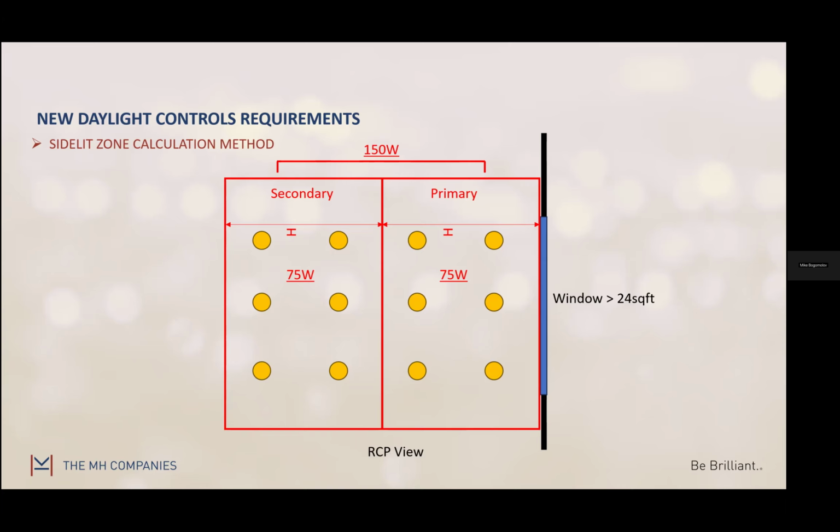Local timer switches. So yeah, schedule based. I guess by timer switches they probably mean a schedule, a switch of some sort that runs a schedule. Yes, you could, and there are devices on the market that can do that. However, when you're using a timer switch, usually those can only handle one circuit. So you basically end up getting stuck with using one per circuit that you have to control.